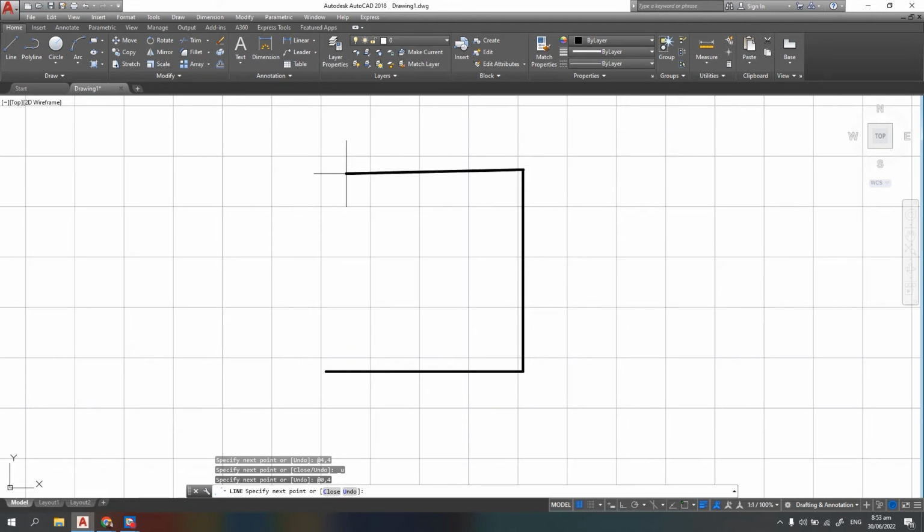That is now at negative 4. Since you don't go up, comma, you have 0. Enter. Then going down, you cannot type 0,0 anymore, but rather you can type @0,-4 because you are going down and this is your last point of entry. Then press enter. Then you have now the square using the relative coordinate entry method.